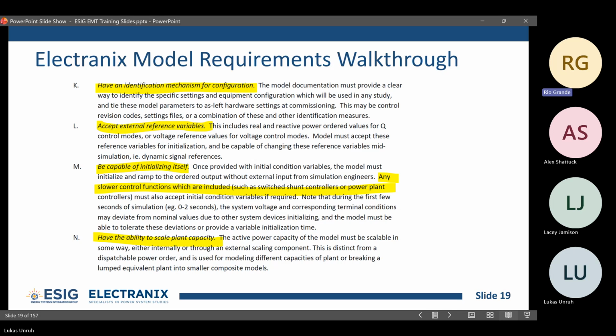This is very program specific, but you can set up the scaling improperly. There's this scaling component, I don't know who developed it, I don't think it's a master library component, where you set a small X value. It doesn't tell you, but it adds a lot of extra capacitance to implement that scaling, creating a traveling wave interface to do the scaling.